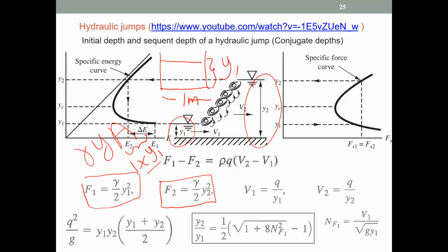That is equal to, if you assume the time rate of accumulation of momentum inside this control volume is 0, then you can write momentum flux out minus momentum flux in, right? That is momentum, you know that you can write m dot, that you can write rho AV, right?